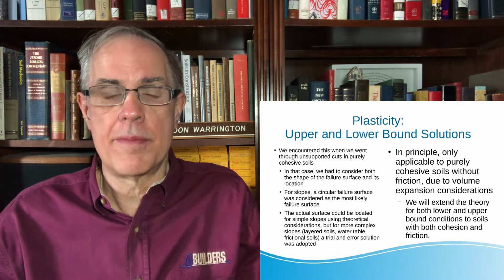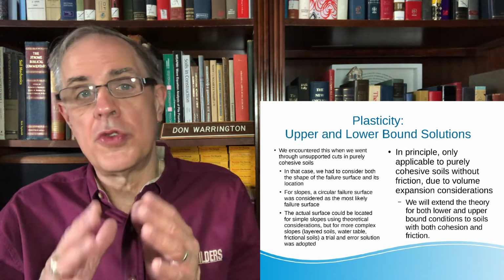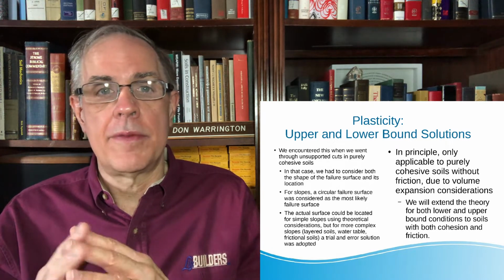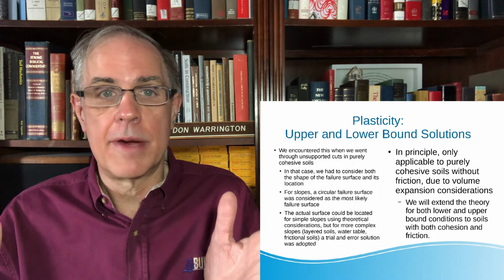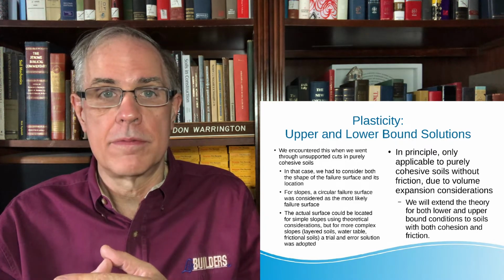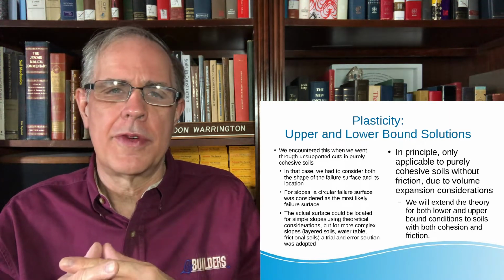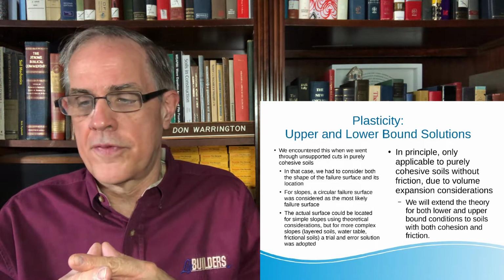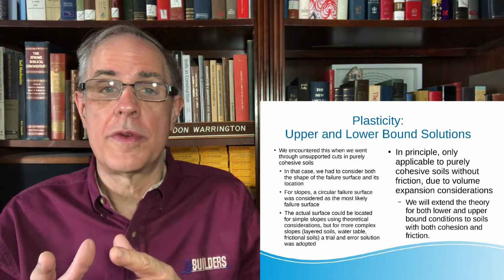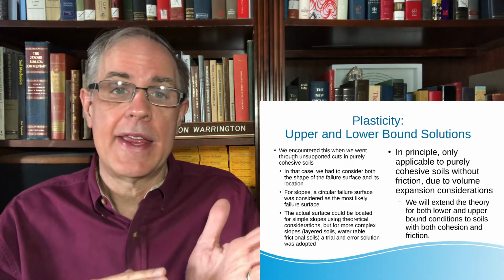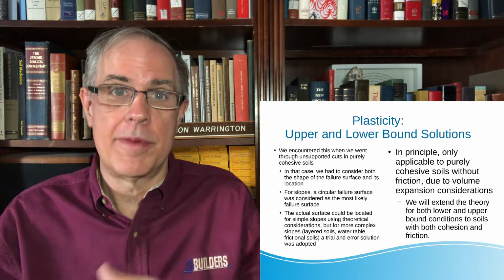So that's pretty much what we're trying to do in bearing capacity: avoid arriving at the upper bound solution, because the upper bound solution will usually be failure. In principle, this only applies to cohesive soils. We're going to show you an extension of it to soils with both cohesion and friction, cohesionless soils, cohesive soils, and everything in between.